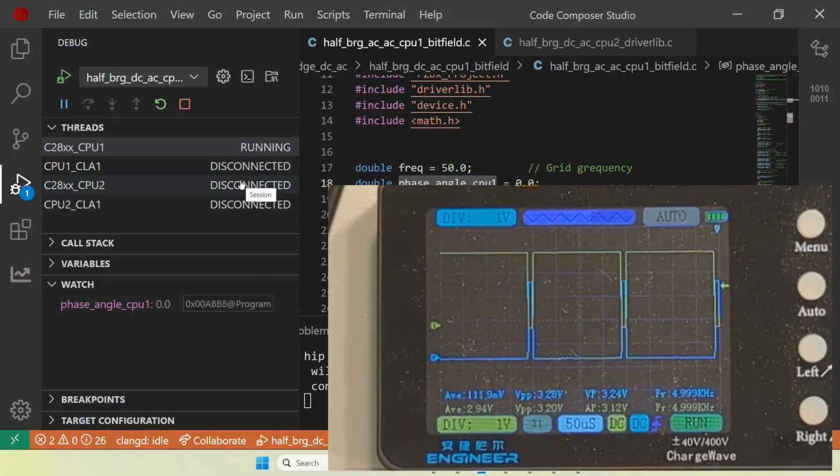Now here, think for a minute and see, we have a cosinusoidal modulation index. That means whatever is the phase angle, the cosine of that is going to become the modulation index. And if our phase angle is 0, then the cosine is the maximum value, which means at this maximum value, the S1 device is going to be on for the maximum amount of time, and S2 device is going to be on for the minimum amount of time, which is correct.